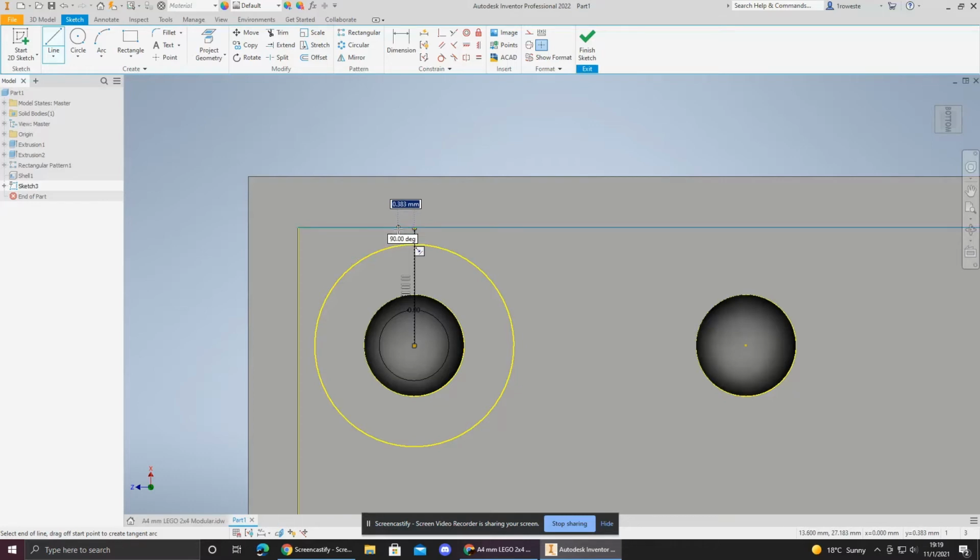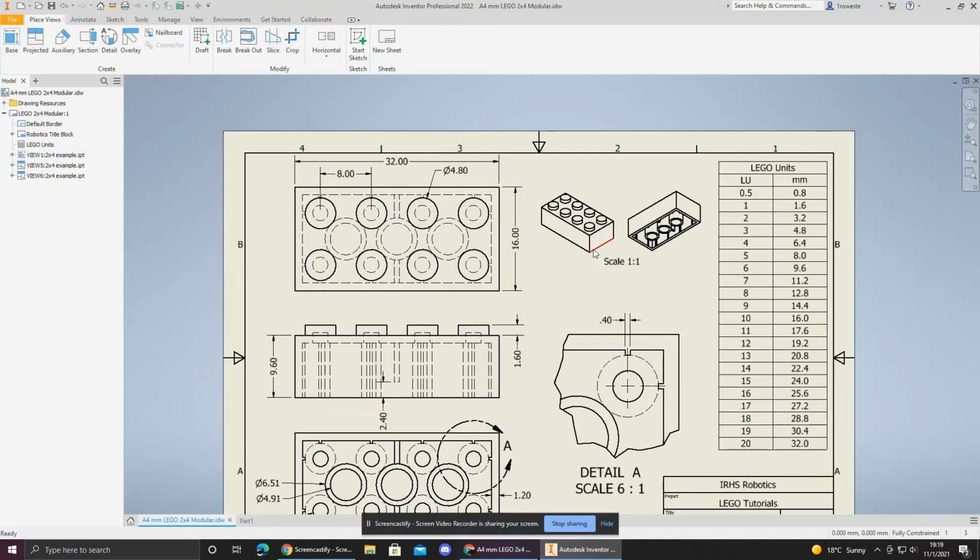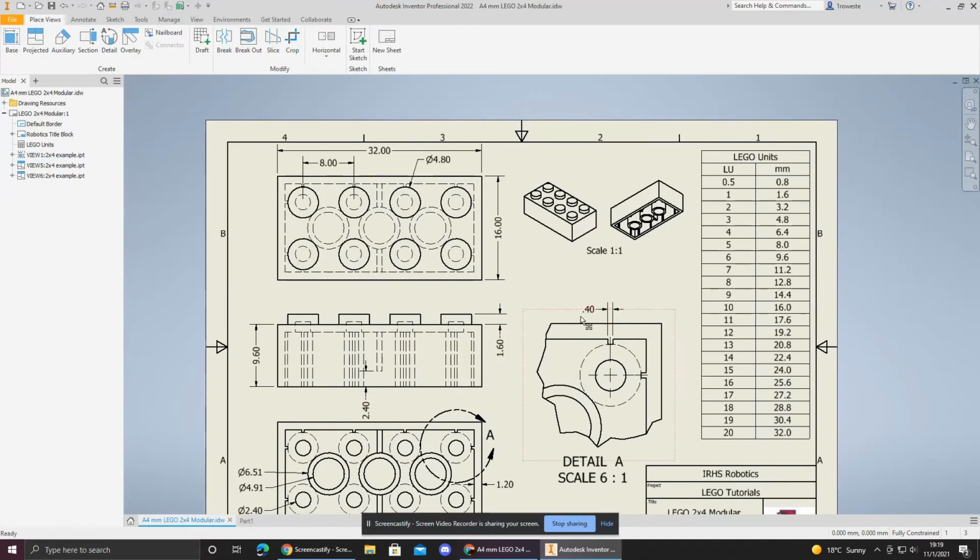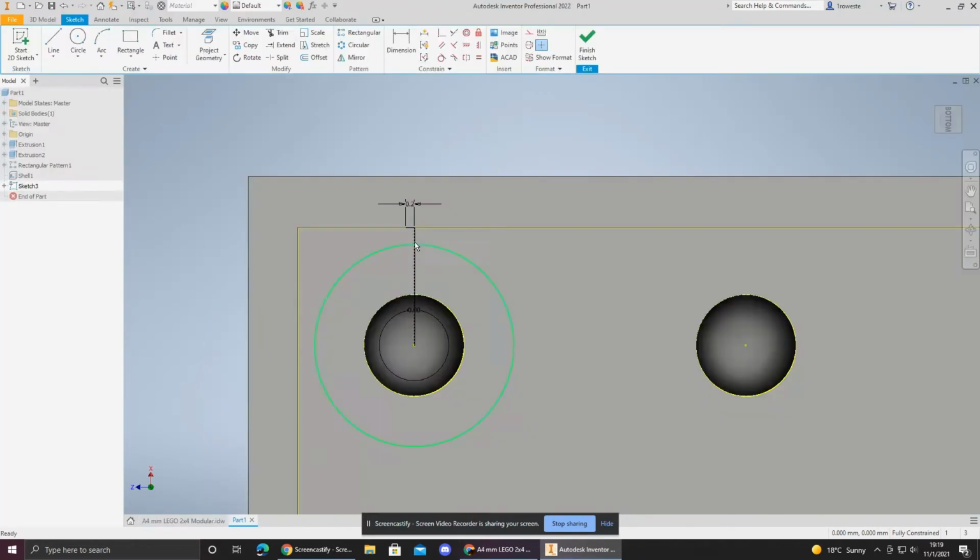We may now use that point to draw 0.2 millimeters, remembering that it is 0.4 millimeters across, so half that, 0.2, seeing as this is the center, and simply then draw a rectangle coming down. Any distance will do. However, we need to ensure that this measurement over here that you can see I've tabbed into is 0.4. We may now press enter.